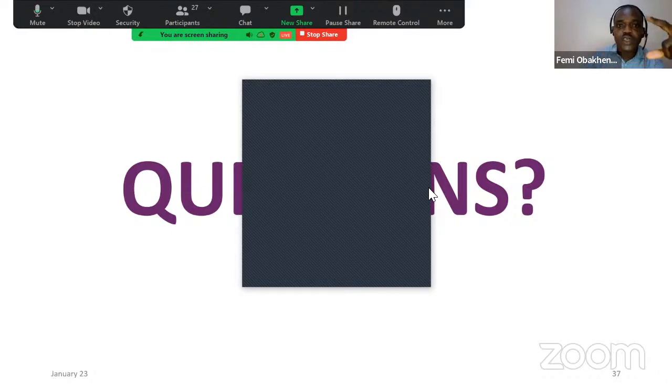But with the analysis that you have done, most times what we do in practice is, even though you have used a base case fracture pressure, you add a factor to it. So maybe 80% of that base case fracture pressure. That gives you some headroom, and you know that you can never go beyond that pressure, so that you're not even very close to that fracture pressure.